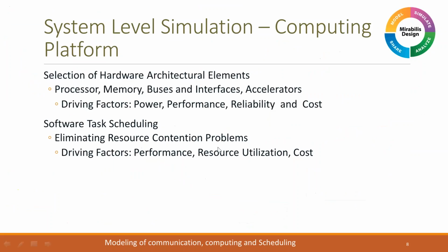That is where the key attributes you want to look at are: how do I reduce the power consumption for every task I'm performing? How do I make it more reliable? Do I need a redundant architecture? Do I need to offload some of the tasks onto an additional core? Answering questions like that. From a software perspective, you're looking at whether you just want to use the standard VxWorks RTOS that comes with a first come first serve, or do you want to use a time space partitioning type architecture and see how much the reliability of your application is increased on the target system.